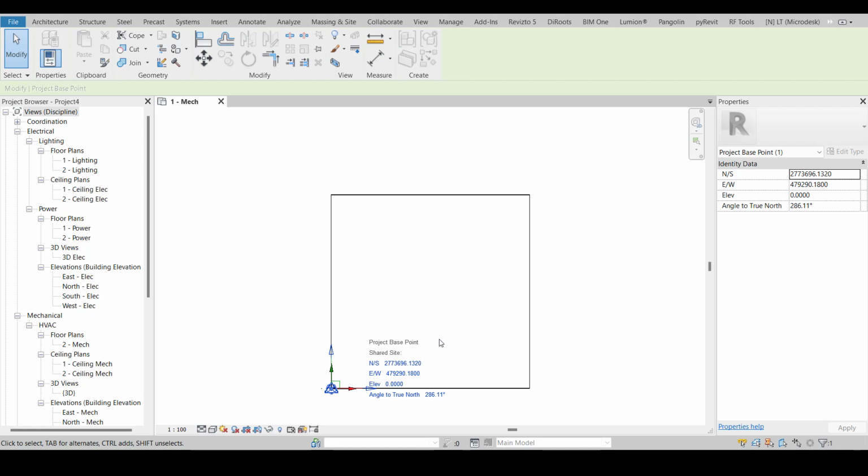So to find out the automatic way, we are setting the correct coordinate system of your project base point. Now this project base point is fixed, and we know that this is the project base point. If someone wants to measure manually from here, like 10 meter by 8 meter, they can do it. If they want to measure it by GPS, they can also do it. So both cases work. That's why we keep the project base point at one point for our complete project throughout the complete construction period, okay. We don't move this.